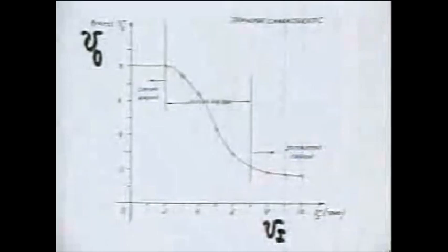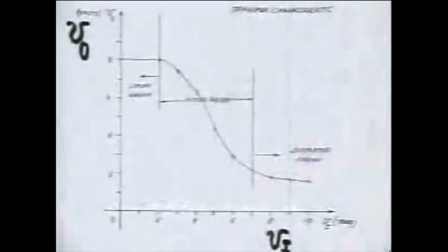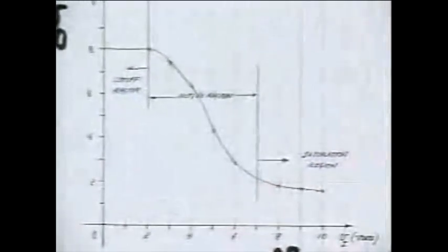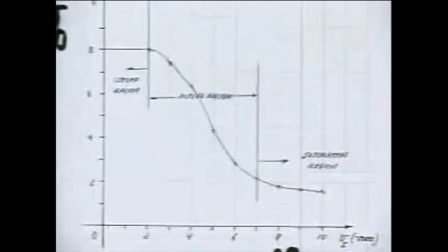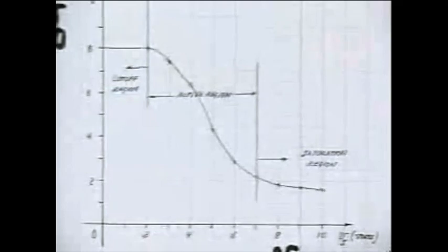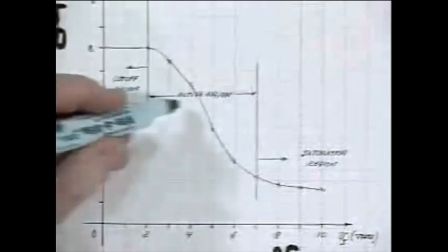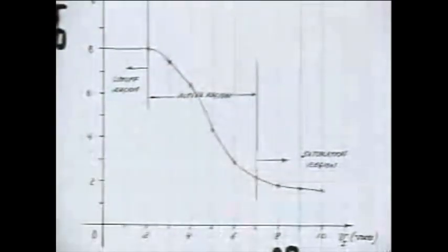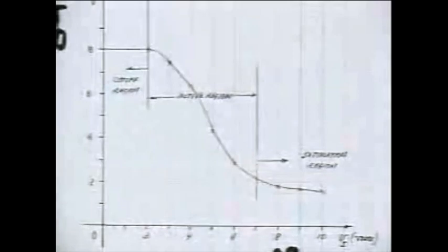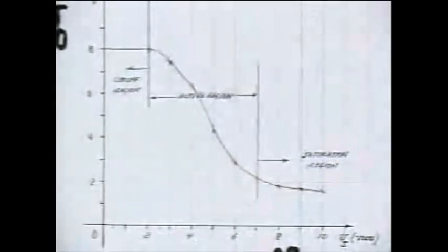This is the same characteristic. Let me blow it up just a little more. I'll cover up the definitions of the voltages, same curve. And I've kind of arbitrarily characterized this as 3 different regions. There is the region between these 2 lines where the nonlinearity is pronounced, and I'll refer to that as the active region. The MOSFET is the first active device we're going to study.